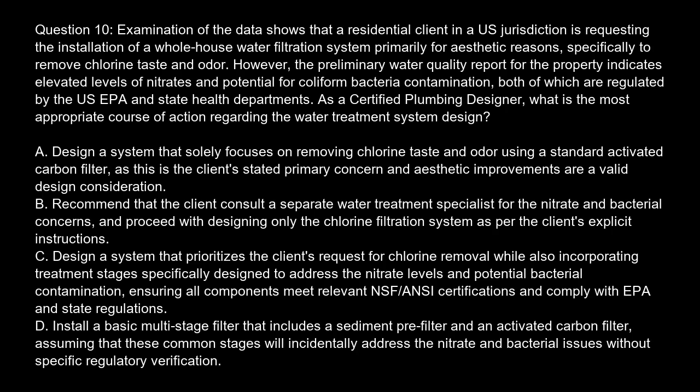Option C. Design a system that prioritizes the client's request for chlorine removal, while also incorporating treatment stages, specifically designed to address the nitrate levels and potential bacterial contamination, ensuring all components meet relevant NSF/ANSI certifications and comply with EPA and state regulations. Option D. Install a basic multi-stage filter that includes a sediment pre-filter and an activated carbon filter, assuming that these common stages will incidentally address the nitrate and bacterial issues without specific regulatory verification.